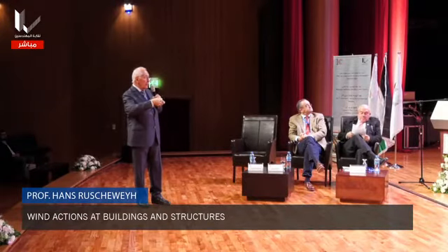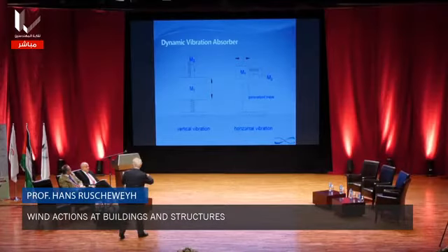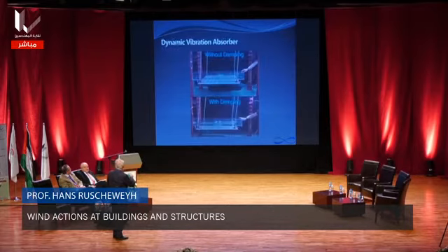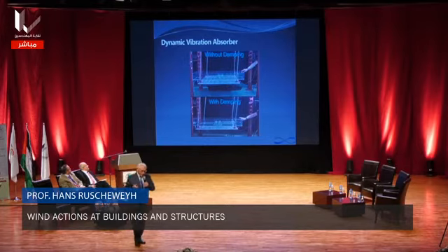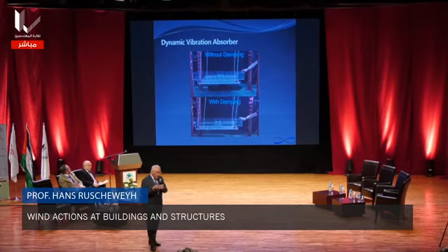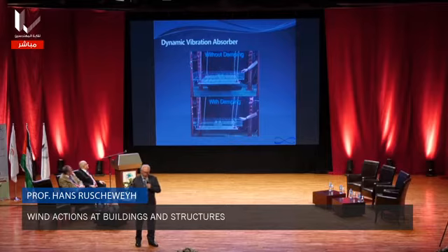This is called a tuned liquid damper. Why does it work here? Again, it is a liquid in a box. And the sloshing of the liquid is the second mass, M2. The frequency of such a sloshing mass can be calculated easily. In every physics book you can read it. But there's no information about the damping effect.